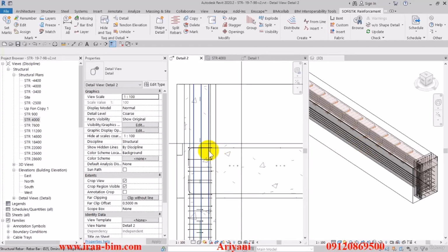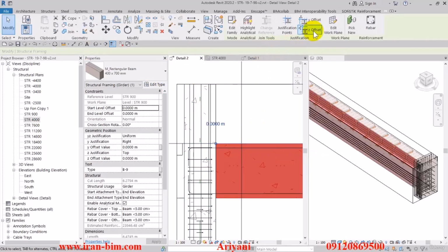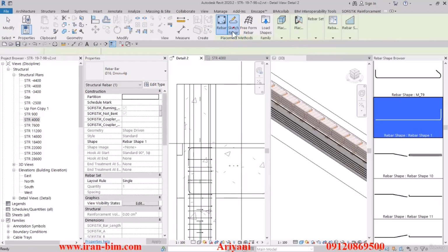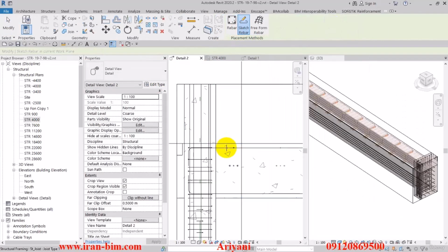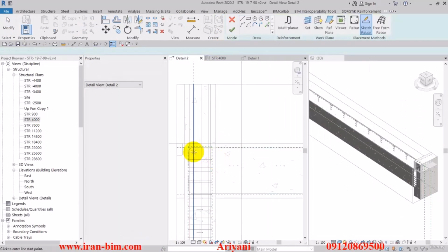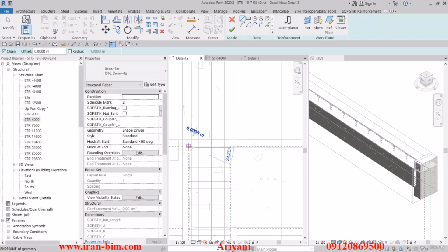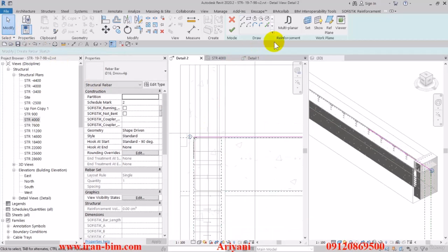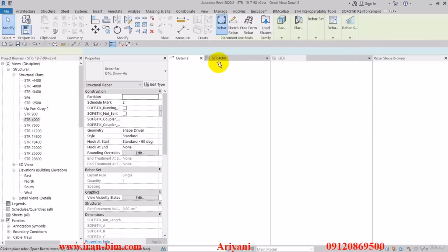And actually right in this point for about the length of 3 meters, we have a type 16 reinforcement rebar and another one that's type 22. So we can select this again, then the rebar tool and the sketch rebar, and then right on this line, set it to 3 meters. All right, then the orientation hook is going to be pointing downwards and then finish it up.